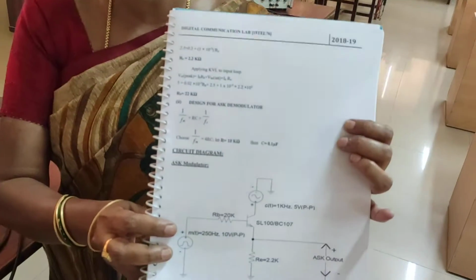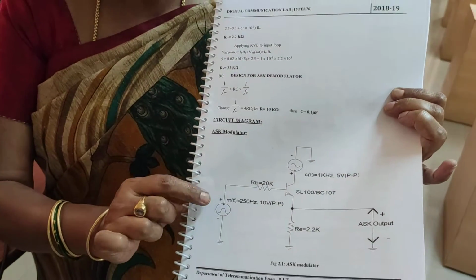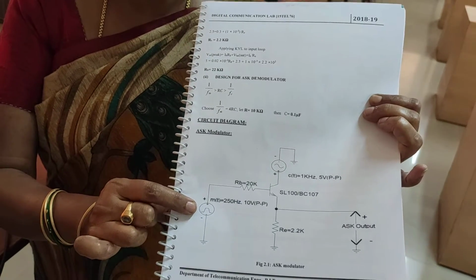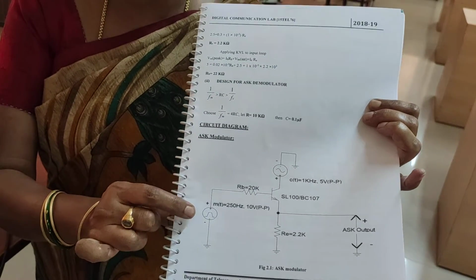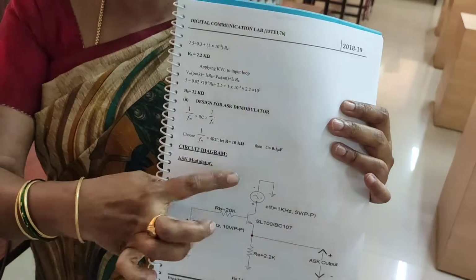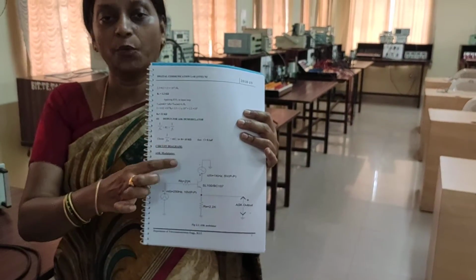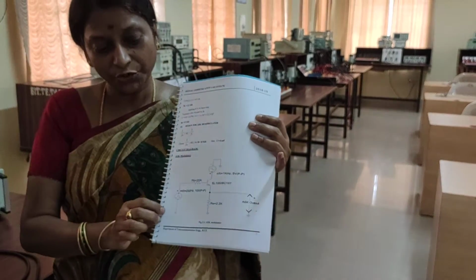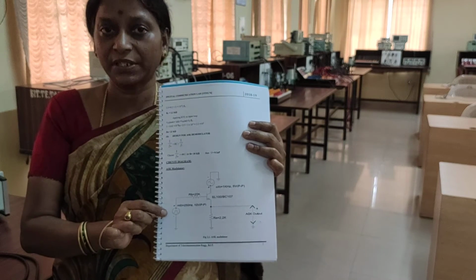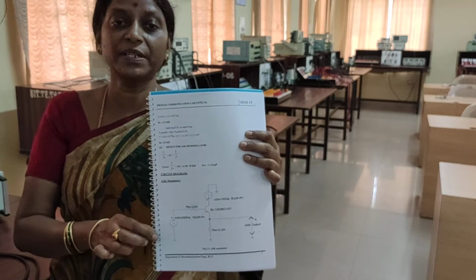This is a circuit for amplitude shift keying. The base is connected to the binary signal, which is an NRZ signal of +5 and -5 volts, that is 10 volts peak to peak. In the collector we have taken a 1:4 ratio of a 250 hertz modulating binary signal and a 1 kilohertz sine wave carrier. The modulating signal is a 250 hertz NRZ square wave, where +5 volts is binary 1 and -5 is binary 0.